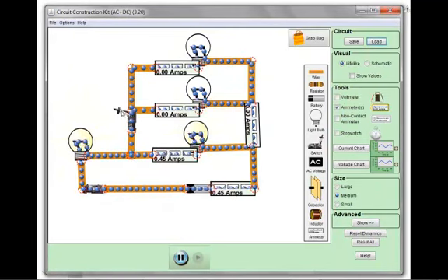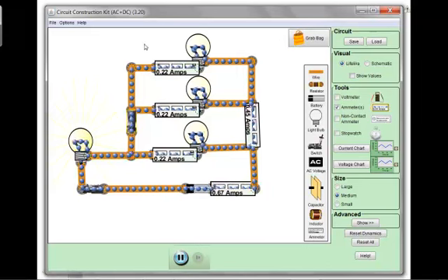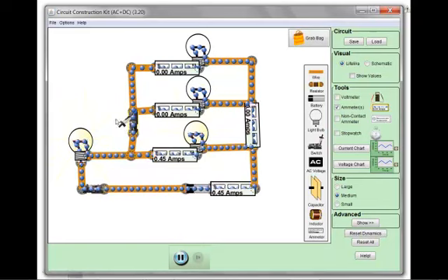So when I close this switch, each one of the light bulbs is getting 0.225 amps through it, and we've got 0.67 amps drawn from the battery. But I open this switch right here. Wait a second, I'll open it. And then these two instantly drop to 0.